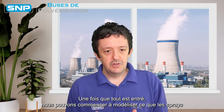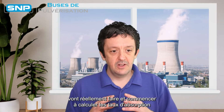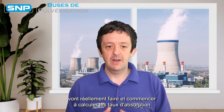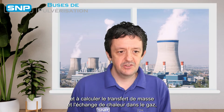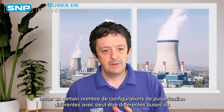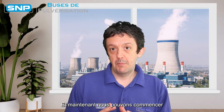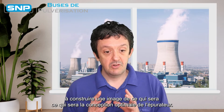Once that's all input, we can start to model what the spray is actually going to do. We can then start to calculate absorption rates, we can calculate mass transfer, heat exchange within the gas, and we can test a number of different spray setups with perhaps different nozzles or different feed pressures, and now we can start to build up a picture of what's going to be the optimal scrubber design.